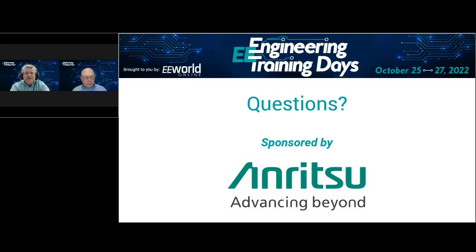Now, if I take a cellular example of a 716 DIN connector, which is the large connector that goes on the Helix type cable, I don't know off the top of my head what the torque rating is, but they do have torque wrenches made to allow the tech to only torque that connector to the amount of torque specified. So yes, you need a torque wrench if you want to properly torque connectors. I'm sure most people listening who work in the cellular industry are probably not using an N-type torque wrench when they're doing their N calibration.